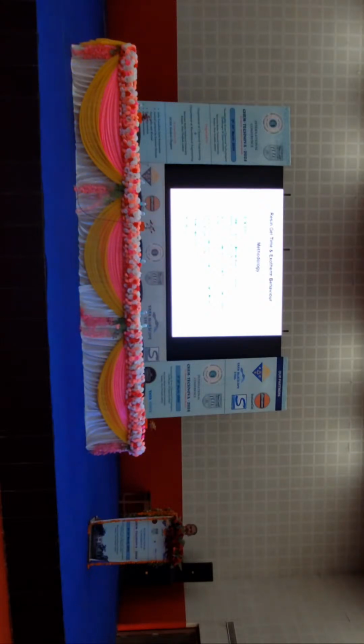Those curing aid proportions also have to be fixed. Here we have varied accelerator volume from 0.5 to 2.5 ml per 100 ml of resin, and cobalt octoate is used as the accelerator. Catalyst volume also varies from 0.5 to 2.5 ml per 100 ml of resin, and we used MEKP, which is methyl ethyl ketone peroxide.